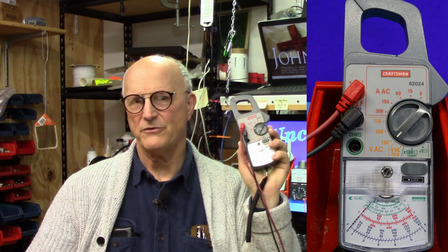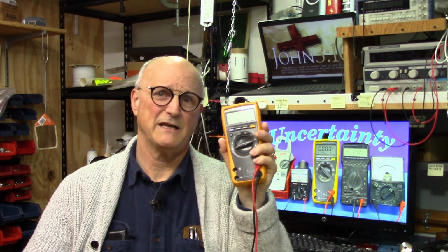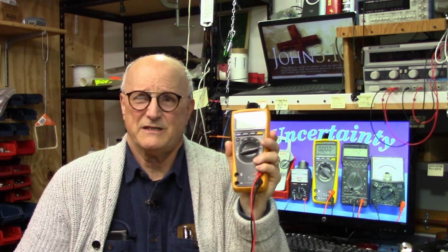Now, most every analog multimeter is different. This Craftsman is 2 k ohm per volt on AC and 4.5 k ohm per volt for DC. And then we have this hardware store multimeter. Well, it's 2 k ohm per volt AC or DC. Now, with all of this said, the digital multimeters generally have a much higher input resistance. Now, I'm not saying that they have an infinite input resistance, but it's certainly a whole lot less of a concern with one of these than it is with the analog cousins.